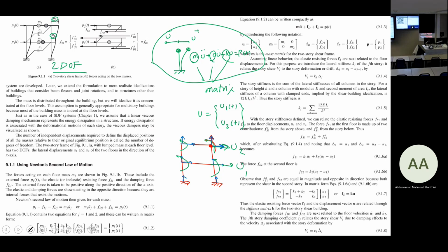And the K matrix is principally the same as what you have done in matrix analysis. If you are not in the dynamic mode, it means that you don't have velocity, you don't have acceleration, you have only Ku equal to P. It's static, it's what we had in matrix analysis, right?